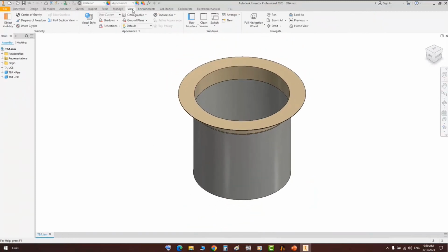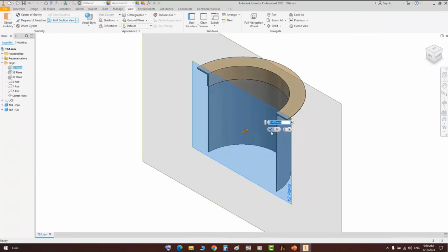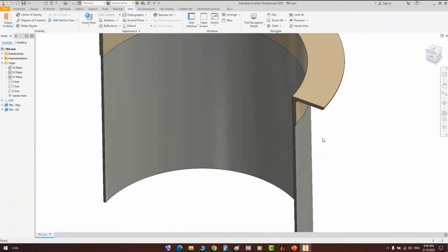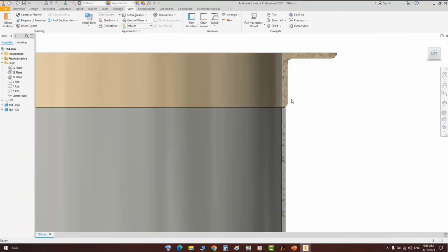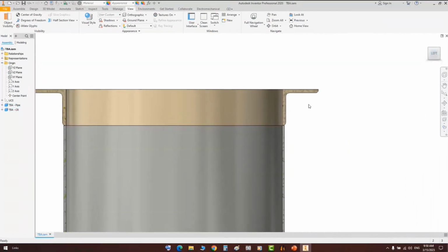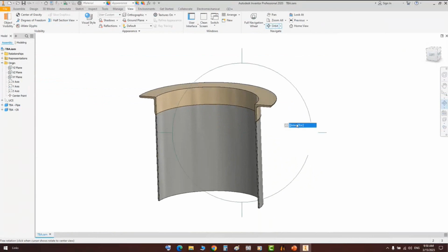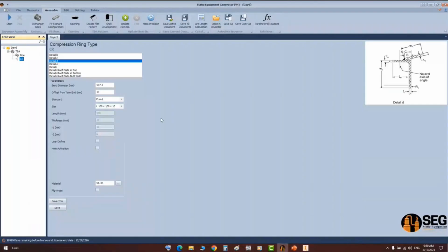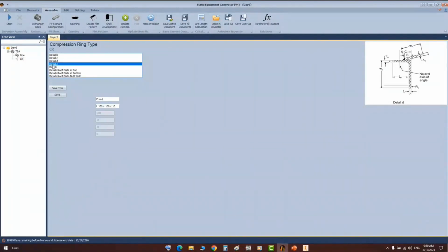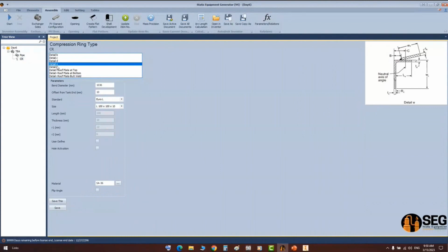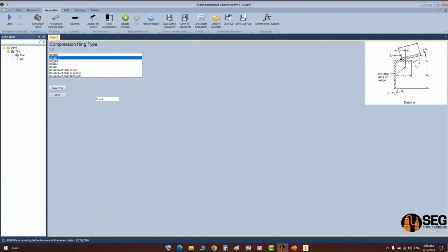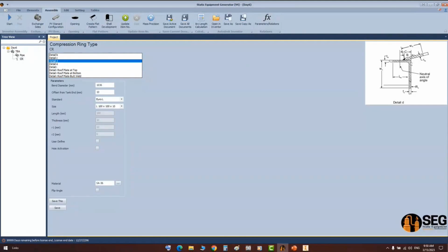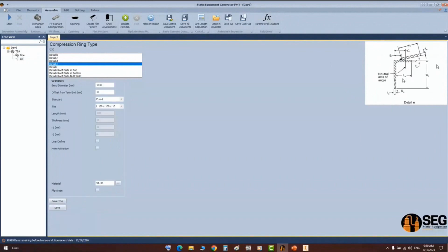if we take a section, half section, for that, it's edge to edge. It will be welded like that, edge to edge. So that's another type for that detail. Another one, which is detail E. It's edge to edge, but the angle will be to inside, not to outside. So the difference between D and E, in D the angle comes to outside, and in E the angle to inside.